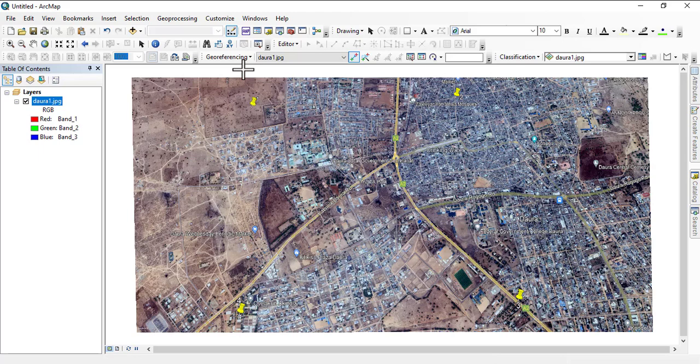What we are looking for in geomatics is to minimize error, not to add to the error. So with this, my recommendation is coordinates. Use coordinates to georeference your image, except when there are none available. In that case you use the other method just to have an idea, then you use an autocorrect image later to correct your data. That, I think, is the best way.